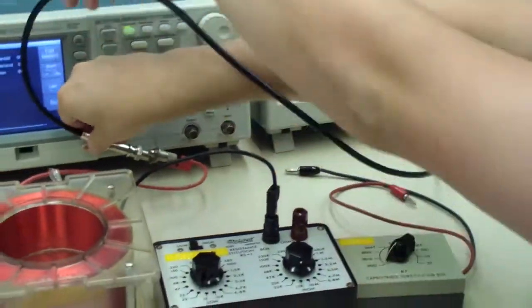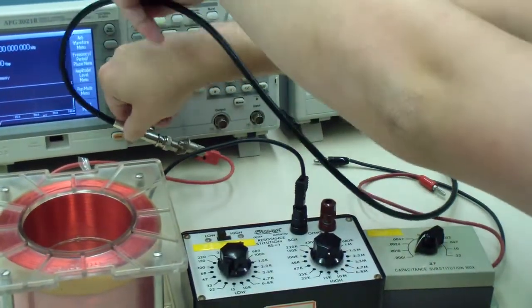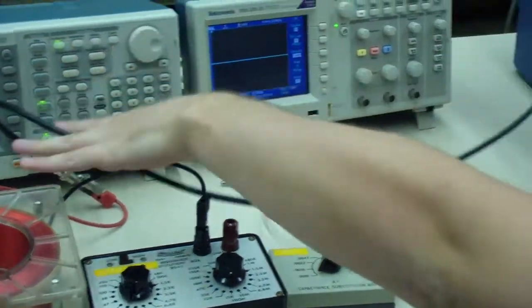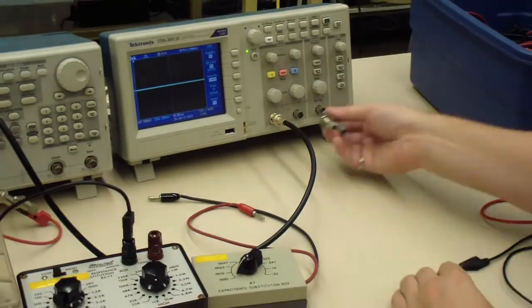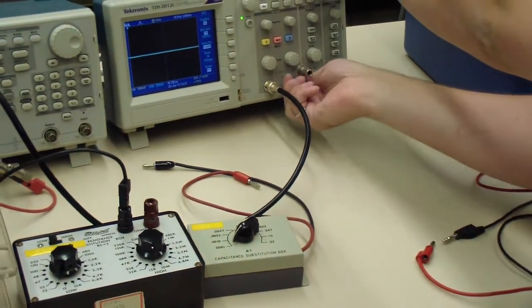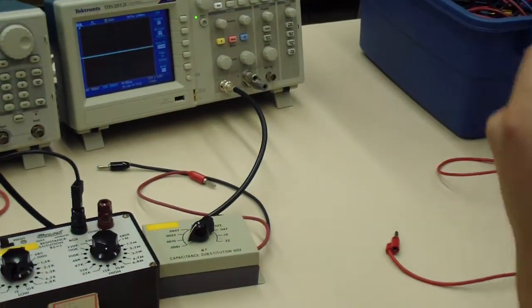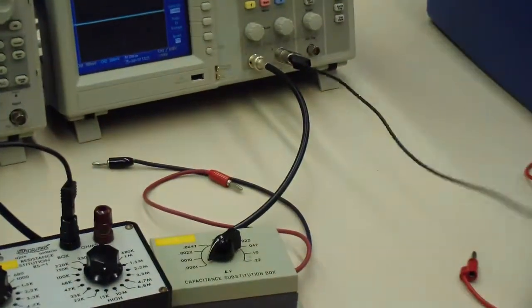Connect the other end of the T-connector to the oscilloscope. Use the second BNC to banana adapter on channel 2 of the oscilloscope. Connect the ground pin, the metal one, to the ground pin of the function generator. Note that your circuit will not function properly if this order isn't adhered to.